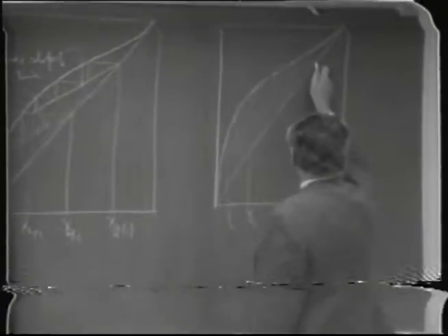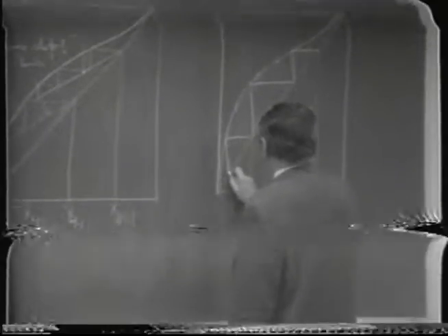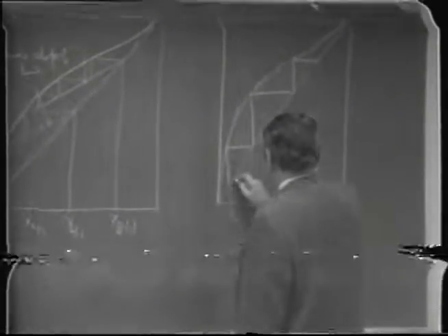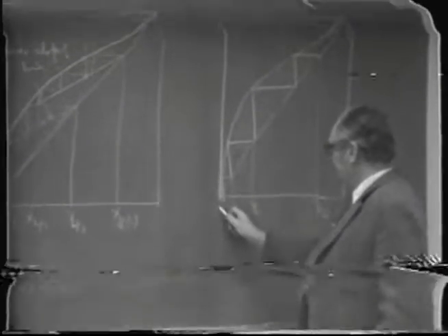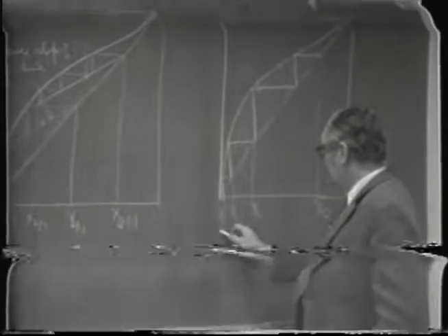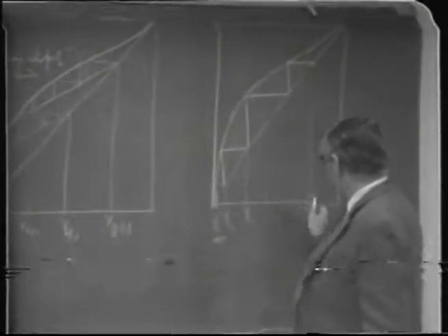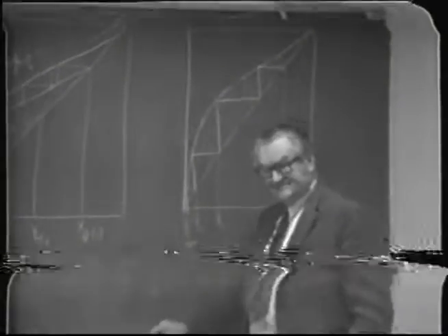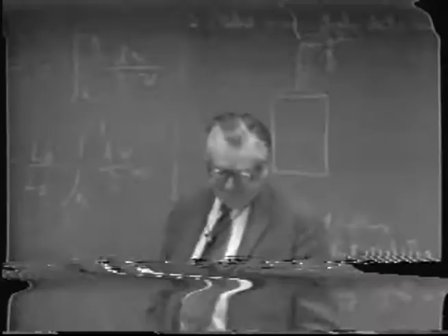So if you had this many, in this case, this would be X sub L minimum that would produce this distillate composition even at total reflux, you see. You approach total reflux.